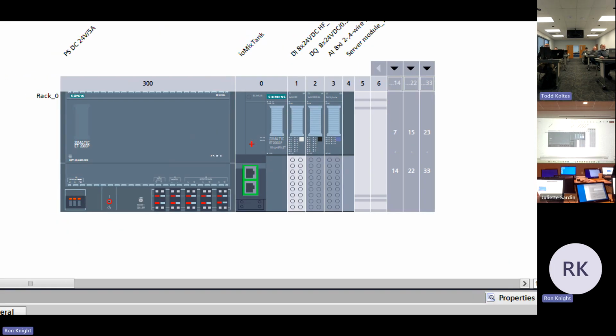Also, I should mention that instead of a communication adapter here, you could actually have a PLC here, an ET200SP CPU. It programs just like a 1500. There is a 1510, a 1512, and a 1514, and there are safety versions of that, so with an F on it. I've got a customer here in Mobile that actually standardized on the 1512F version. So smaller footprint, lower cost point, not as much memory or as powerful as the full-blown 1500, but depending on what it is you're doing, it's a great PLC.